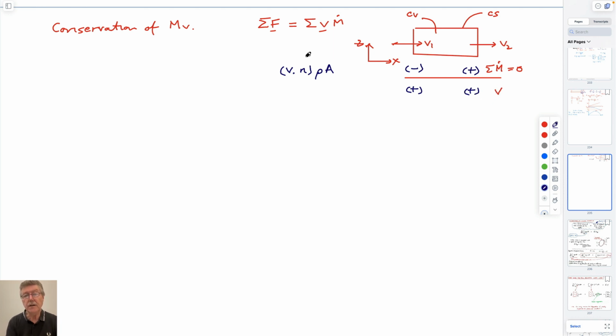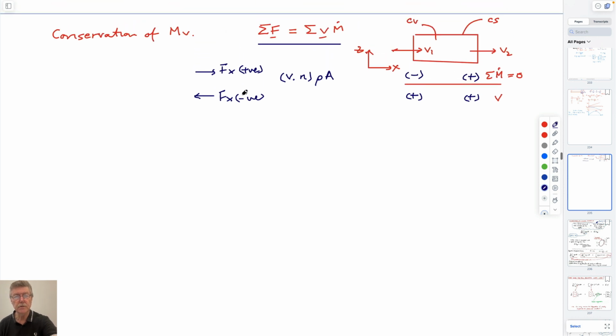So if you multiply these together, as you need to get here, then you need to be mindful of what those mean. Out of the system for mass flow rates is always positive. The pre-factor acting on this is always in the Cartesian direction. Likewise, the forces would be positive. This would be a positive force. This would be Fx negative. Yeah, you'll get used to it. Just have to be consistent with your coordinate system.